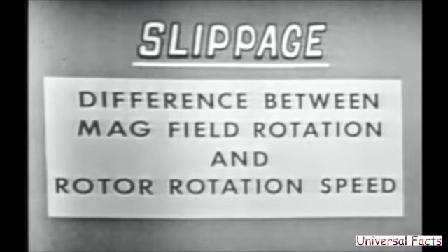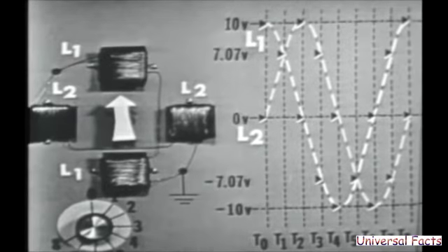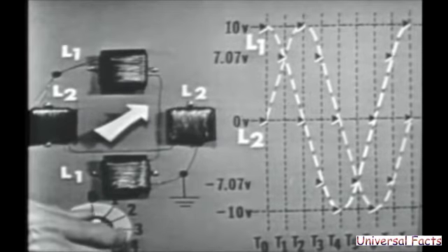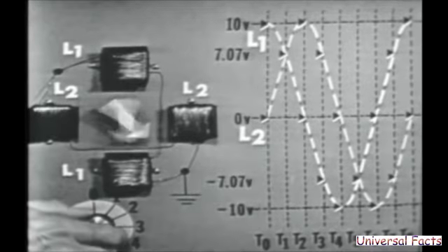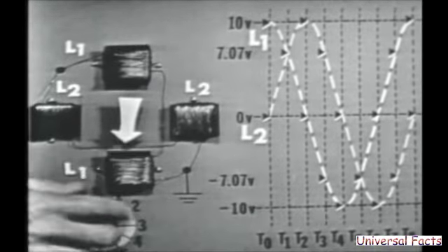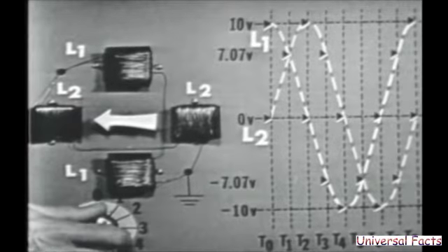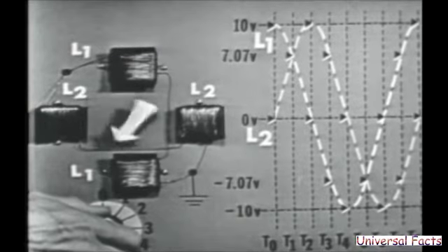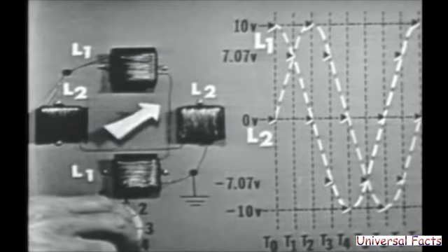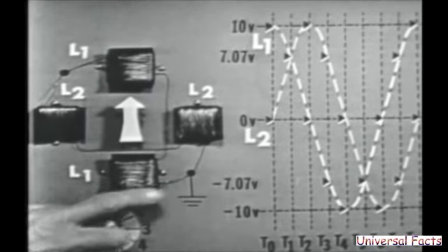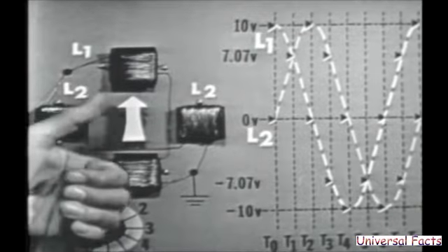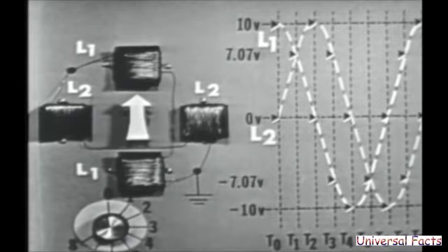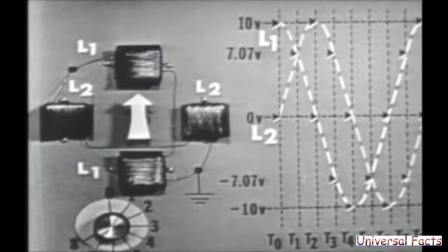Now, can I get item 7? I'll get it, all right? All right, you can have it. Item 7 shows you how one complete revolution of the magnetic field is accomplished by applying these out-of-phase voltages to the stator windings. Now, you can study this very, very carefully so as to fix the principle in your mind. And, by the way, we might point out, Tom, once again, that you can apply the left-hand rule to all these coils and prove precisely what we've said, right? We can develop a rotating magnetic field.